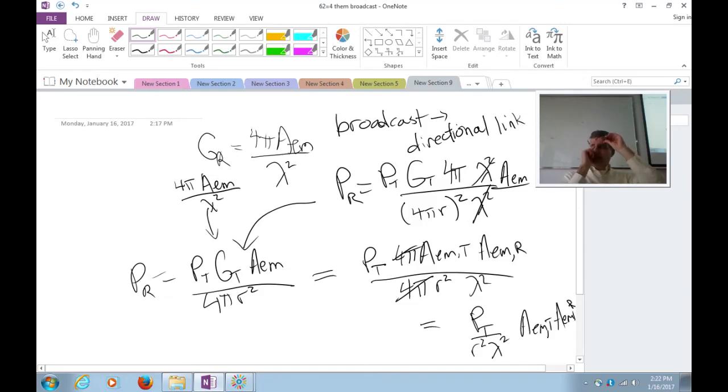So when we're broadcasting radio, let's say we're broadcasting FM radio or AM radio, or even VHF television, that's a broadcast to an omnidirectional user, and it's beneficial to use low frequencies for that. So that's why we use low frequencies for those applications. Aside from the fact that, as a point of legacy, it was easier to build electronics at those lower frequencies. There's still a big demand for those low frequencies because they propagate so far, and it's very easy to build these broadcast applications for that.